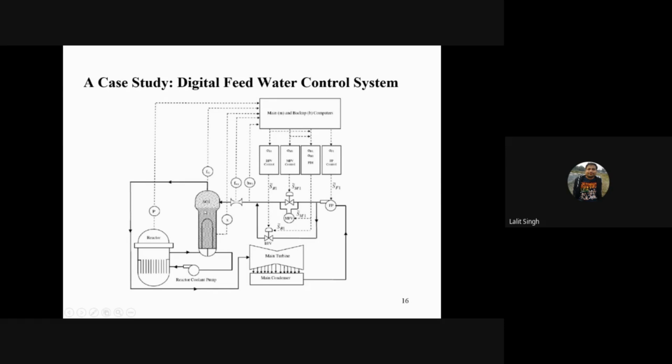And so basically what happens in the steam generator, it contains two logical portions. The lower side is filled with the normal water, and the upper side is empty. And when this hot water, almost more than 300 degrees centigrade, flows in through the steam generator, this normal water suddenly converts into steam, and because of the lighter density it gets accumulated on the top portion. And then it is connected to the turbine through a set of valves, where it can drive the turbine